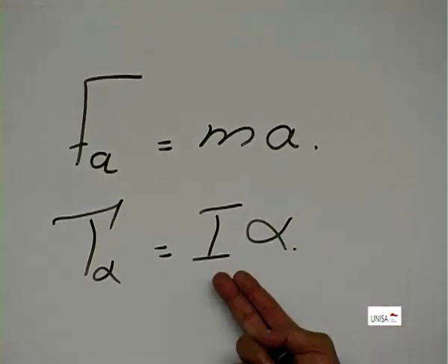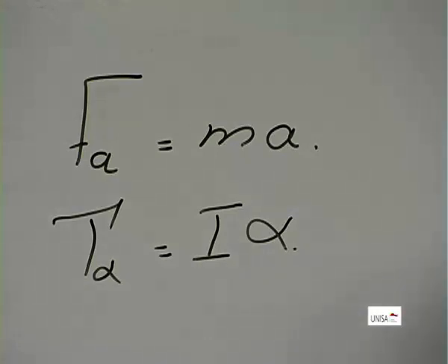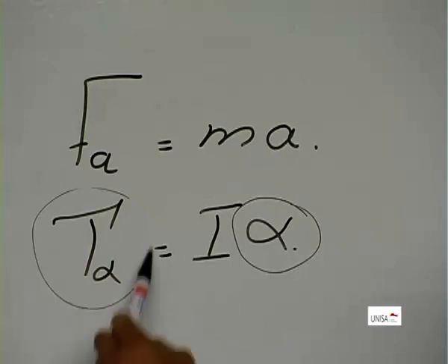You can calculate the inertia of that specific link. By the construction of the velocity and acceleration diagram, you can find the angular acceleration. Then you can work out the torque acting on that specific link.